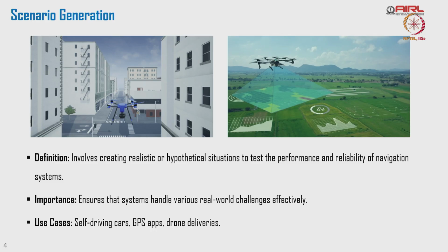Think about it: if a drone has to go for servicing or firefighting, the drone enters into the building and you are applying a trajectory tracking control, with X, Y, Z to be tracked. Suddenly I enter the building, and my LiDAR says my height is only 2 meters, but the height of that particular floor is, let's assume, 3 meters per floor. We are looking at the 4th floor, but suddenly the drone starts climbing up, and you will have a problem. So what we mean by height is very important when you are talking about a terrain or a mission.